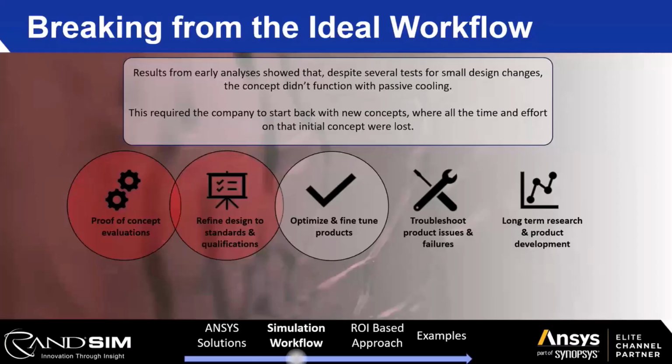There was no way it could stay below the necessary temperatures for a bus bar to survive solely based on passive cooling. It was largely due to restrictions from fluid getting into the bus bar environment itself because of constrictions in the louvers going in. And what that meant is because they had skipped those first two steps, they had lost effectively all the work.